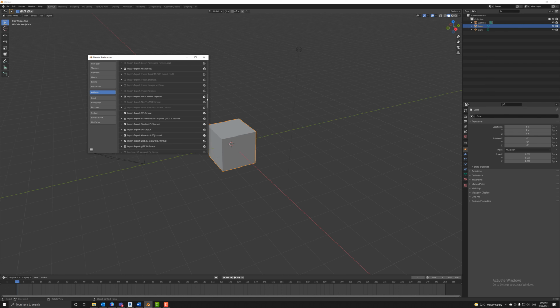Make sure it's ticked. While you're in here, just a bit of a quirk of Blender, there's a whole bunch of things down in this tool layers that are not enabled by default. You can see the Object Carver tool, for example, is not on. I don't think this Boolean tool is enabled by default, so just go in and enable that while you're in there. I found that was quite useful for cutting out the site from the finished context.